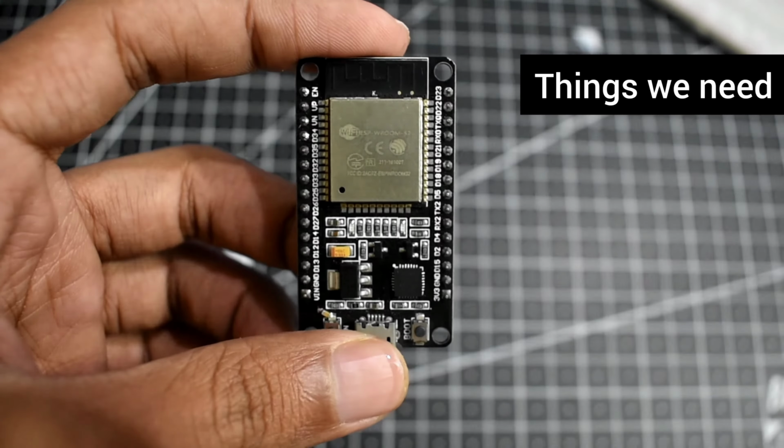So this is the DHT sensor. I'm going to place this as well. Now please note, if you're just using the sensor, consider using a pull-up resistor of 1K at least. Then let's connect the wires now.